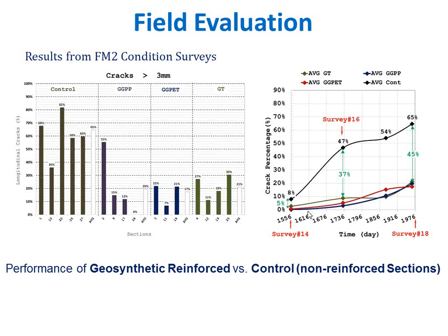I could say that if the dry season would have lasted 6 months only, this could have been a very drastic difference. After 6 months, cracks started appearing on the reinforced sections. So there is an unambiguous conclusion: reinforced sections worked to mitigate problems associated with expansive clays. Now, which one is better? Well, all three geogrids or geosynthetics that have been chosen have performed equivalently. So if our KSGC has some merit, it should give us equivalent values.